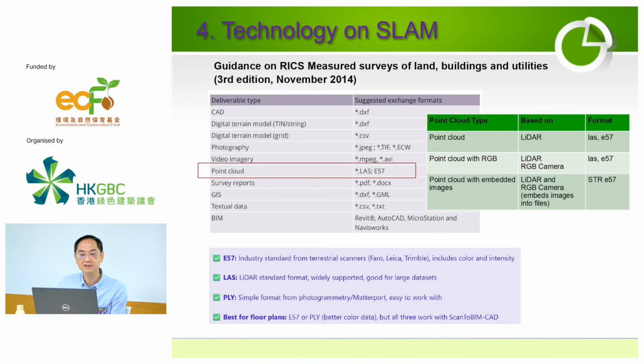According to the RICS, the Royal Institution of Chartered Surveyors, the point cloud should have LAS and E57. If it is brand new SLAM equipment, you should have the format not only LAS but also E57. When we choose suitable equipment, we also need to check whether it has the structured E57.